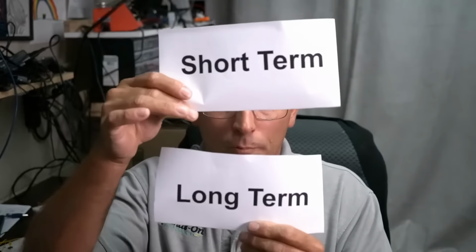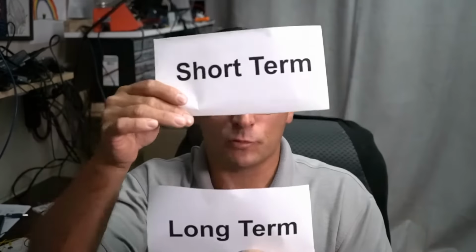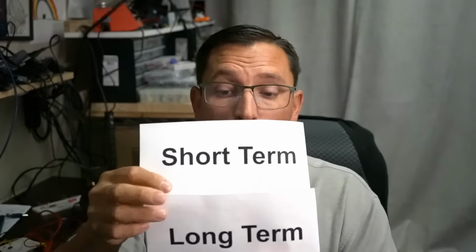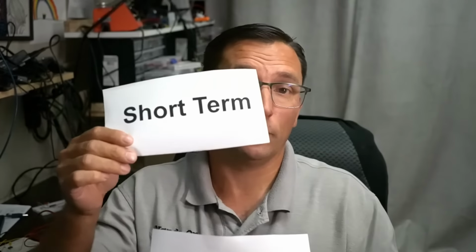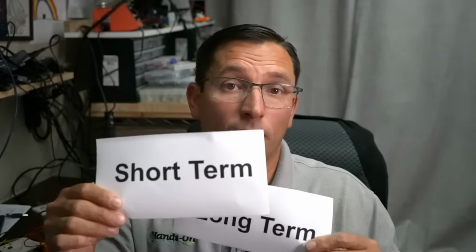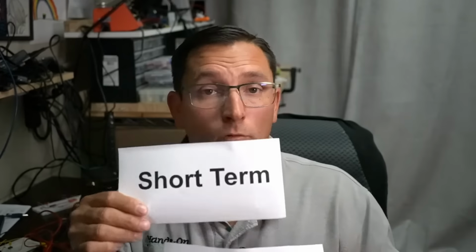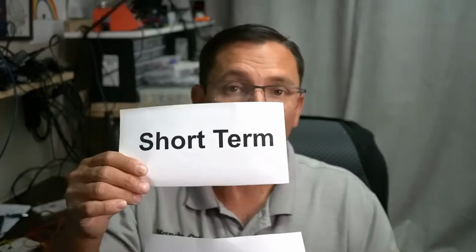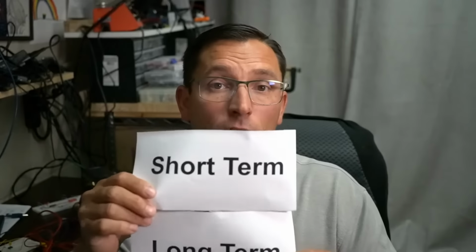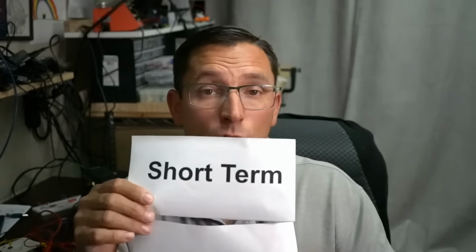So we start this car up, and I don't care if you say your long term's on top, short term's on top, it doesn't matter. If we have +5 long term and 0 short term, that's the same as having +5 short term and 0 long term. It doesn't matter. Long term doesn't mean we're adding more fuel than short term. Long term is just telling us, hey, we had to make this correction over a longer period of time.